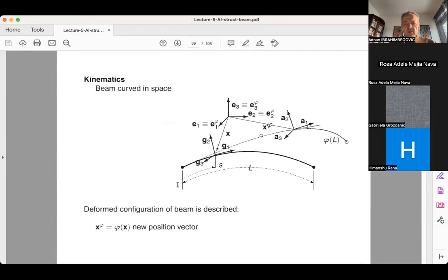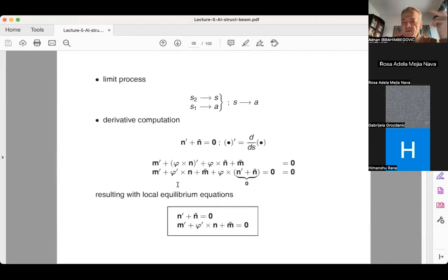So once you have these equilibrium equations, you have to ask yourself, okay, what are these stress resultants possible to pair with? And please note that I can establish this equilibrium equation on the exact form of the beam, where S is used as the really curvilinear coordinate that is parameterizing this. And we studied this curvilinear cable element, and we saw how, using isoparametric elements, this computation with respect to S, of the derivative with respect to S, could be easily obtained by appealing to the isoparametric interpolation.